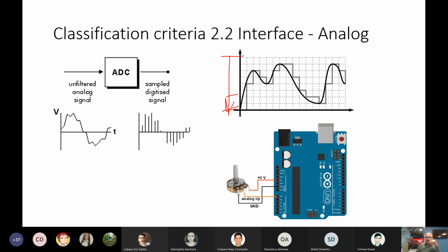This is the resolution. We can say that we have how many values, or we can say that we can have 2 to the power of x, x being the x-bit resolution of the signal. Yeah. So once again, here analog infinite resolution. Here we will have, let's say, 10-bit resolution. That means we'll have some